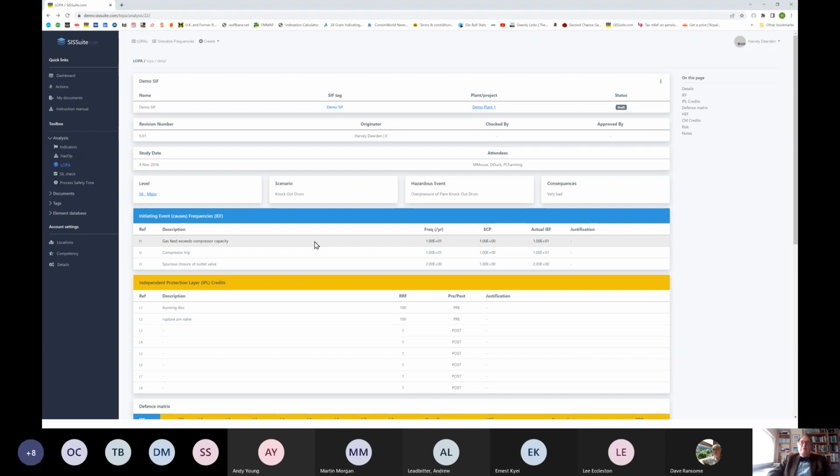But as long as you're aware of that and make provision for it within the LOPA calculation, in truth, I don't see a problem. So here we have multiple initiating events that we're looking at. Total of 22 a year as things stand. On a more complete record, we'd be entering the justification. You know, there's free text fields here, so we'll be entering the justifications for those entries there.